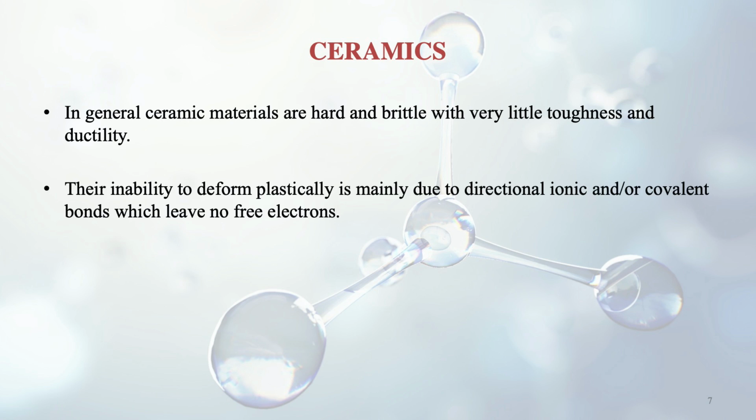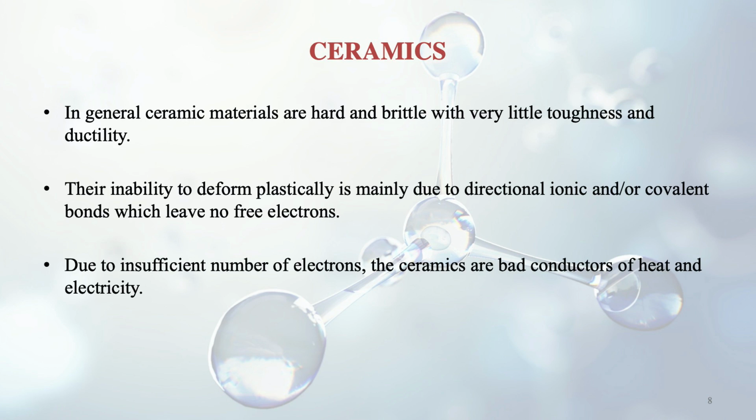And they have an inability to deform plastically. Obviously, when they are not ductile, they will not be plastic as well. What happens in the inner structure is that, due to the directional ionic and covalent bonds, they leave no free electrons. So due to the lack of free electrons, they are not plastic. Due to the insufficient number of electrons, another thing comes in: they become bad conductors of heat and electricity.